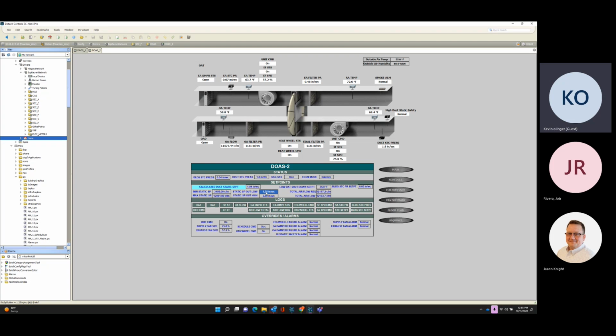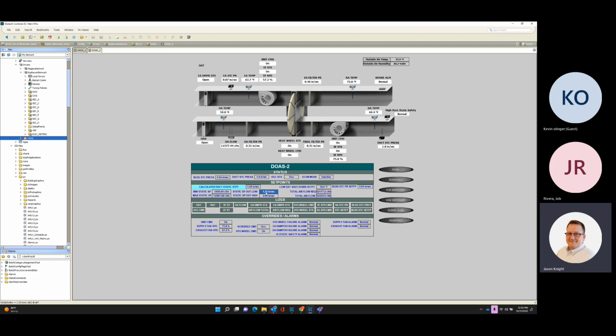Okay, because I'm assuming in my mind, even if we're getting the volume we want, if there's a discrepancy down in the field or a problem with the box or whatever, we could starve out a box, but it's through the TAB and everything. They've determined that 1.25 guarantees some of our furthest boxes are getting what they need, I'm assuming. Correct. So TAB, what they did was they had us set everything at min speed or min flow for the VAVs. And then we ran the actual unit at 1.25 inches to see if it would produce enough air to meet that min flow set point.